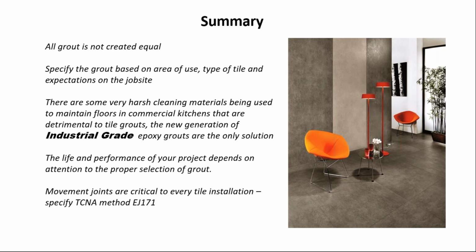Make sure that you specify the grout based on the use, the type of tile, and the expectations of the job site. Explain to your owner that if you don't want to be maintaining the grout and sealing it, and the possibility of it staining, a Portland cement grout, or a cement grout, period, might not be the way to go. There are very harsh cleaning materials being used to maintain floors in commercial kitchens that are detrimental to tile grouts. Make sure that the new generation of industrial grouts are what you're using in your commercial kitchens. It's the only solution that will work.